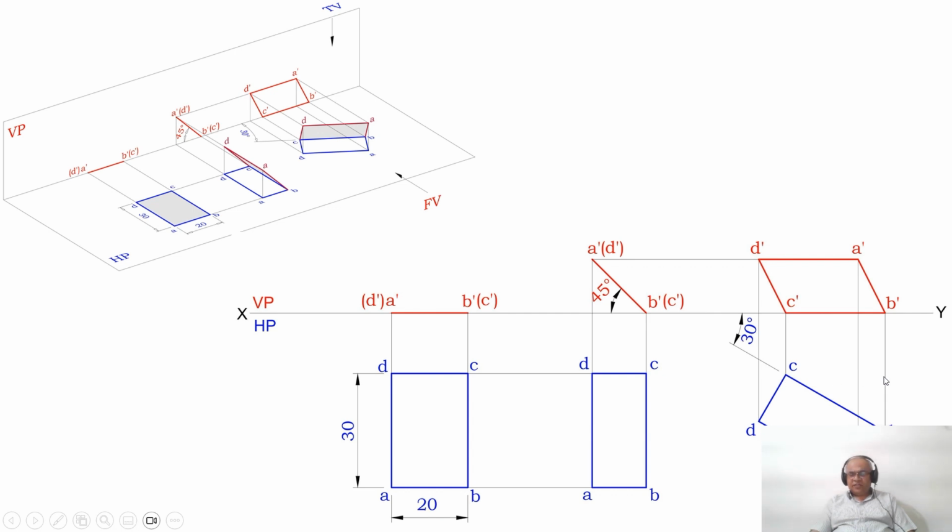with respect to that horizontal line, you measure an angle of 30 degrees downwards and draw an inclined line. Then by using the compass, you measure the distance from C to B with C as center. Mark this point as C here. With C as center, cut an arc on that inclined 30 degree line. So you mark that point as B. From C, now with respect to BC, you have the protractor here. Then with reference to this line, you measure an angle of 90 degrees and then draw a perpendicular to BC.